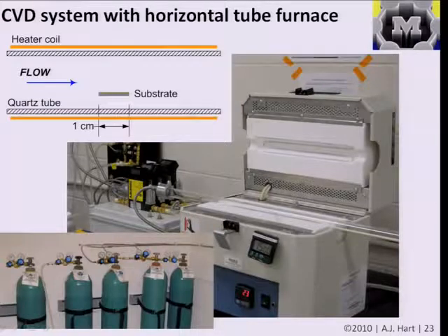And this being a schematic of what's going on here shows that you might have a small piece of a substrate, such as a square centimeter piece of a silicon wafer, and it would be sitting in this hot sealed atmosphere where these heater coils determine the temperature and where the sealed tube determines the gas flow, and you would execute a program of chemistry and pressure and temperature to get the process that you want to happen.